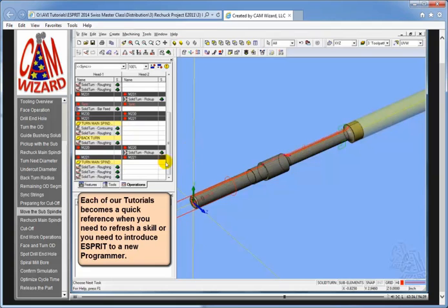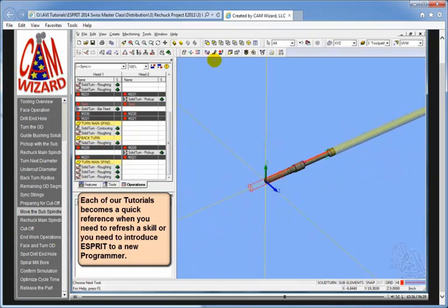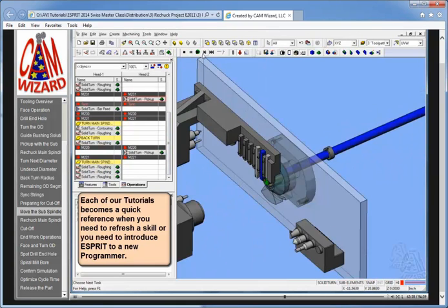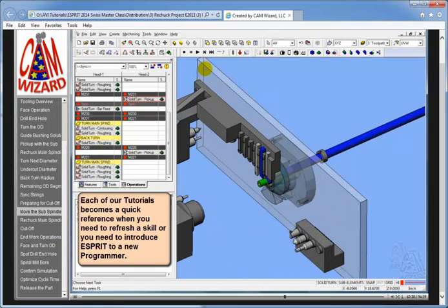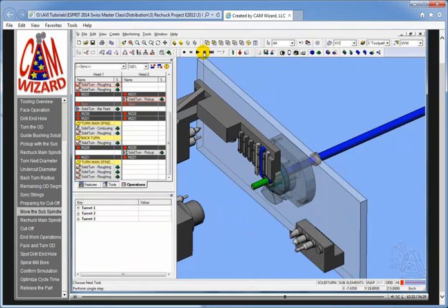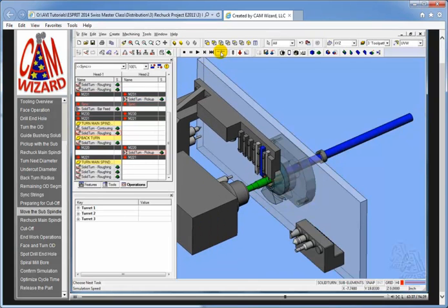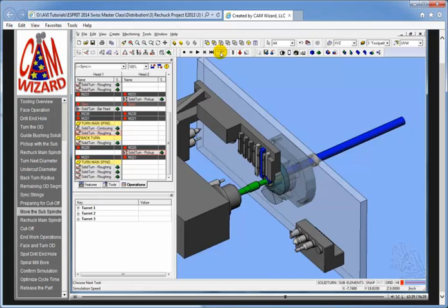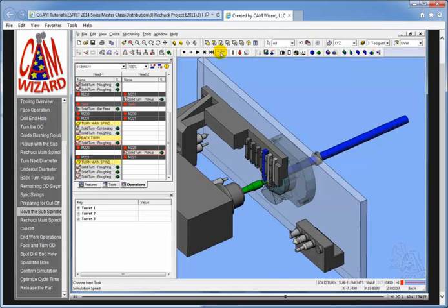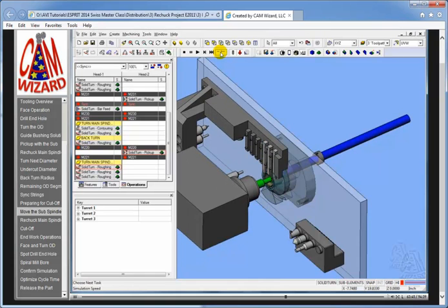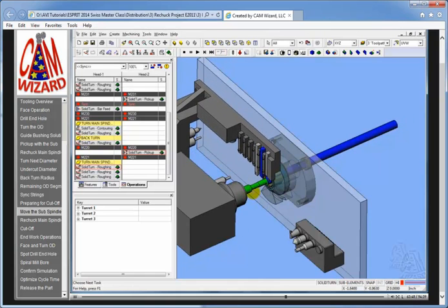Okay, now, once we're to this point, let's run another simulation, refresh our memory. Do the holes, drill, come in. Okay, it's going to come up and grab the first pickup. There it is. And now it's holding it at 2 inches. Now after this turns around and does the back turn, like so, we're going to come back in and do another regrip against that shoulder. So we're grabbing as far as we can with that tool. All right, good.